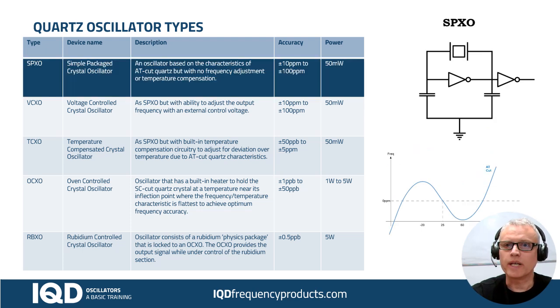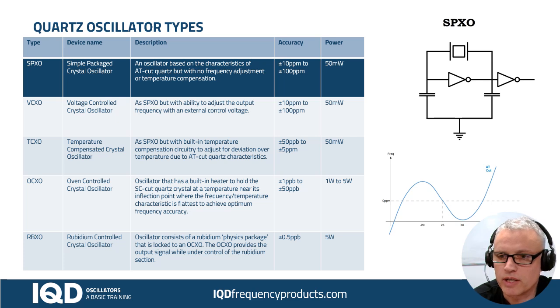Then we come to the next slide where we're going to show a simple packaged crystal oscillator. Here we're going to incorporate that rock into a basic circuit to make a resonator. Looking at the circuit, you can see the amplifier represented as a buffer in the middle, a second amplifier which isolates what's happening on the feedback circuit from the outside world, and then a couple of capacitors.